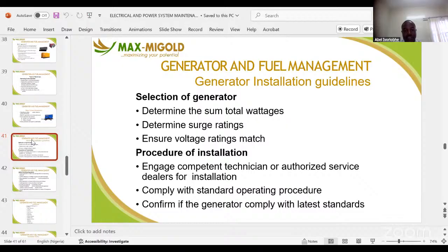So when you are selecting a generator as well, you determine such rating. That's why I say you give allowance on the circuit breaker that you put. So the circuit breaker can tolerate some level of disturbance or distortion without tripping the generator. But if it's beyond what the circuit breaker can tolerate, it's the limit, it will trip the generator for protection.